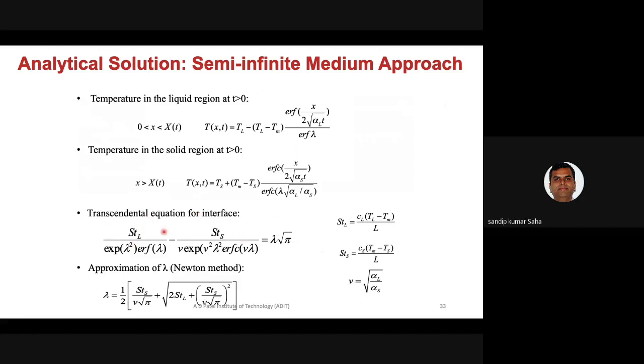Nowadays MATLAB or other types of software are available. You can easily code this to get the solution. Earlier days we needed to do some iteration process to solve this type of transcendental equation. However, if I see this equation, what I can see is that I am getting the liquid phase temperature as well as the solid phase temperature, and I am explicitly calculating the melt front.